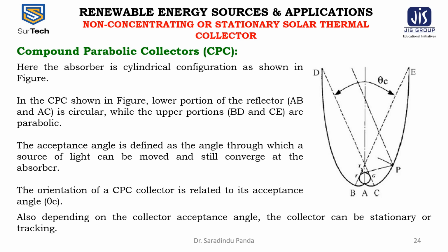It can also be stationary, but radiation will only be received during the hours when the sun is within the collector acceptance angle. When the concentrator is oriented with its long axis along the east-west direction with a little seasonal adjustment in tilt angle, the collector is able to catch the sun's rays effectively through its wide acceptance angle along its long axis.